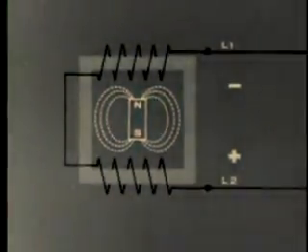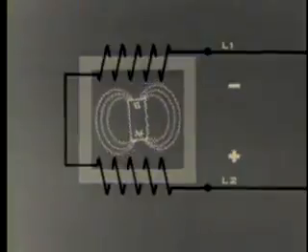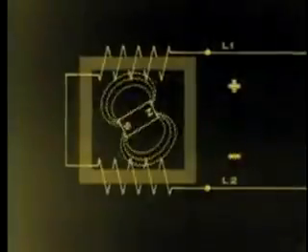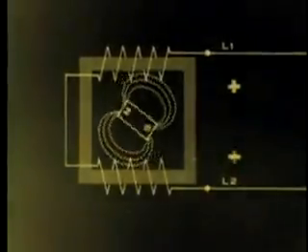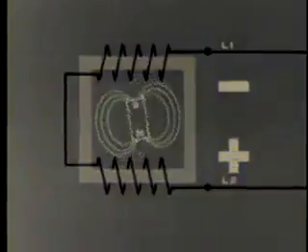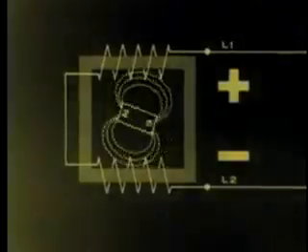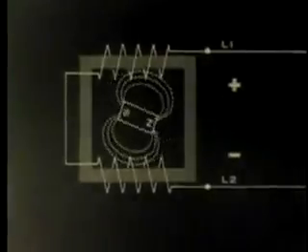Each time the magnetic lines of force of the magnet rotate across the wires in the coil, a potential is induced. Because of the difference in polarity of the magnetic poles, the induced voltage is alternately negative and positive. When we connect this generator to our line, it will create a signaling current alternating at approximately 20 cycles per second.